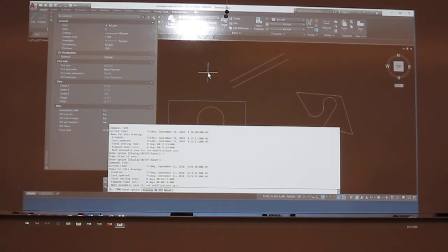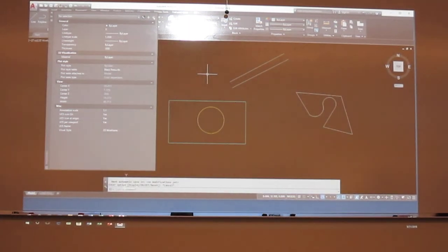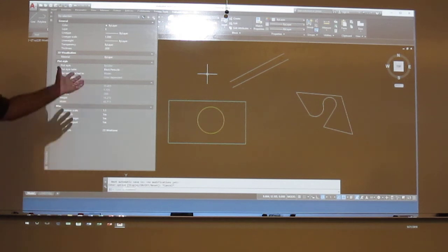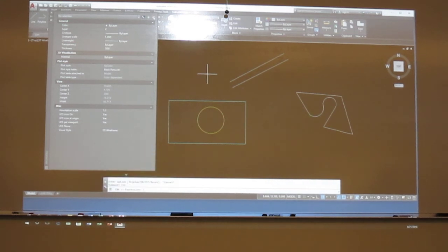Okay, the time command. So make sure you can see that. All right, the quick calc is next. In fact, I think that's really the last thing in the chapter to kind of deal with. We do have a pretty good calculator in here. But before we go into quick calc, let me show you another way to do calculations really quickly if you need to. This thing's got a calculator going all the time, and I haven't really seen this command in a text. But if you would, type CAL. Okay? CAL. Okay, and then hit enter.